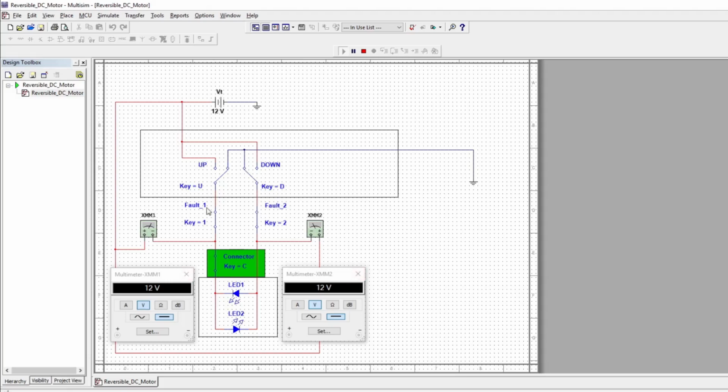Now, depending on what you have from there, if you're up at the switch, you can check these lines. So sure, you can unplug this whole gang switch, send power down, right? And if that motor doesn't turn, you know you have a wiring problem or a motor problem. And as well, again, you haven't tested the validity of this pin here or this pin here to flow the proper amount of current. You haven't checked these switches in all their different positions. But as a quick initial test, all else being equal, if you do have access to that motor, you can do a lot of checking down this way, and it is quicker, all else being equal.